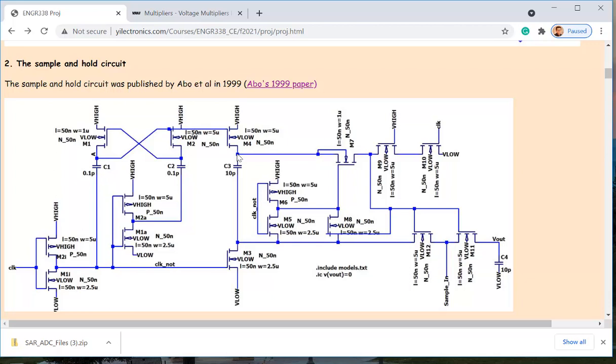And now I'm adding something to here, like AC signals. AC is going to pass to the other side, right? But is it able to change the voltage across the cap? No, it's not changing it. But what's going to happen is that the AC voltage, which is actually the signal, will be added to the VDD on the top, like a VDD DC voltage on the top plus that AC swing. So no matter what the V in is, the voltage here will be V in plus VDD.